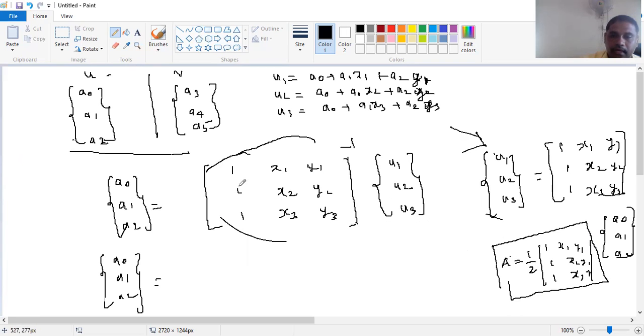When you calculate the inverse of the matrix, you get the value like this, and this value has been considered as the area of the triangle ultimately, and we can write this as 1 by 2A. So plus you get 1 by 2A into x2 y3 minus x3 y2. Here we get x3 y1 minus x1 y3.